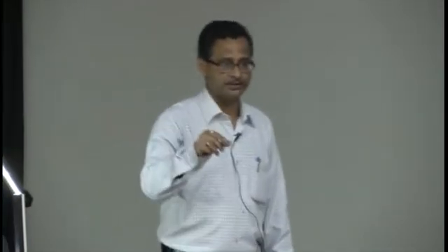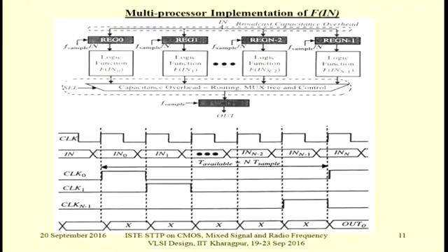So what do we gain by that? If more time is available to perform some task, it means that the voltage can be brought down, is it not? Because the drive current is provided by the voltage. And if you require less drive current, because now the device can operate slowly. So parallelism, what it does is that each of the elements is allowed to operate slower. And if it can operate slower, it can afford to take a lower amount of voltage, right?